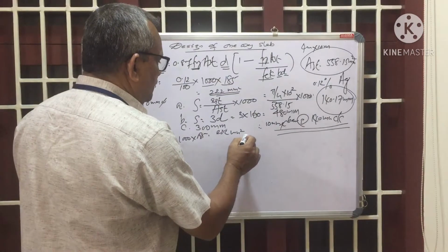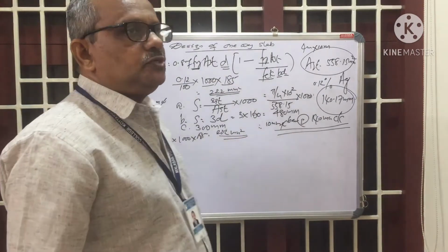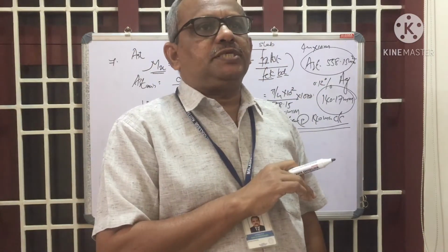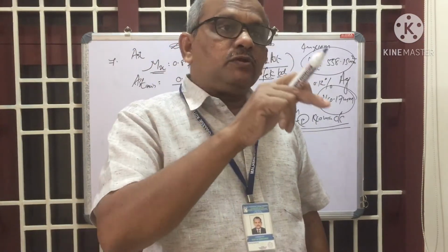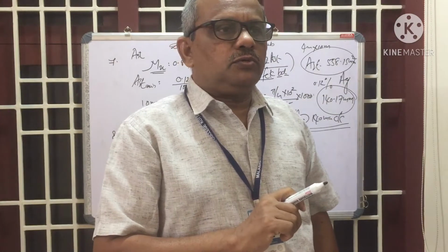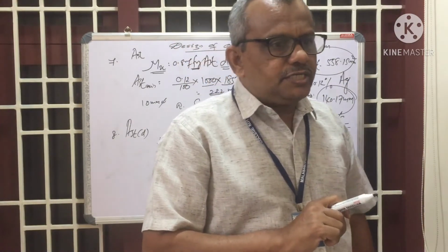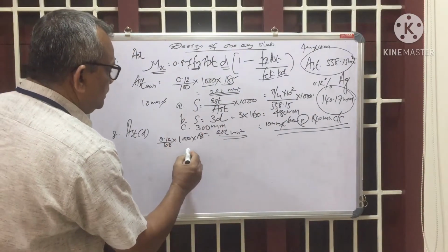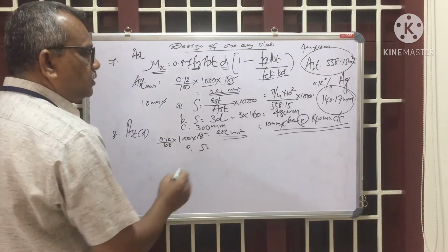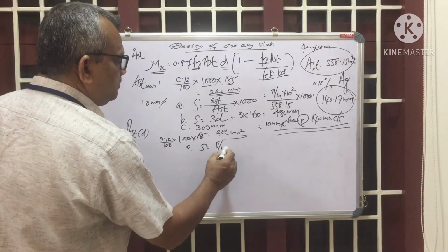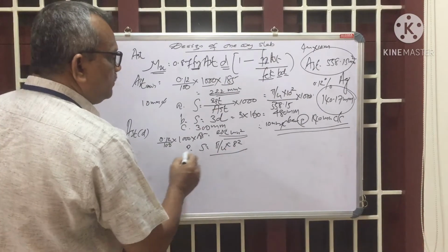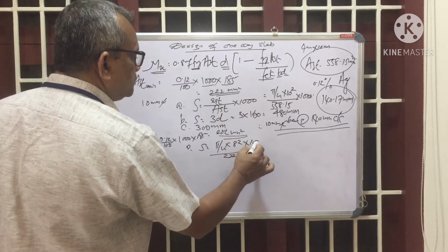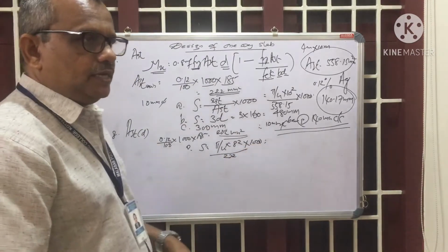Here, main reinforcement assumes a 10 mm diameter. Now distribution steel, usually the diameter will be less than the main reinforcement, so we assume 8 mm dia bars as the distribution steel. Then find out the spacing. S is equal to small ast, pi by 4 into 8 squared, divided by capital Ast, which is 222, into 1000. Is it clear?